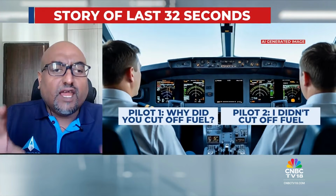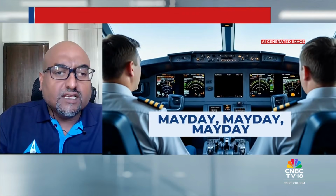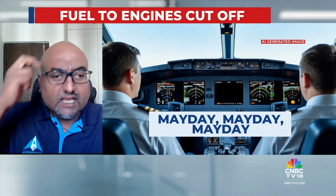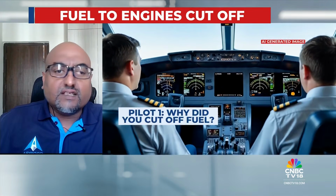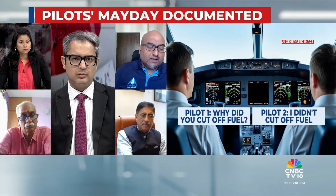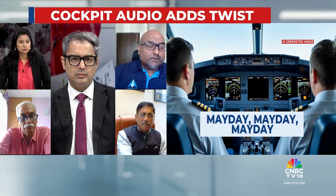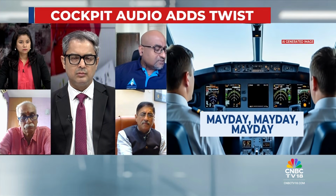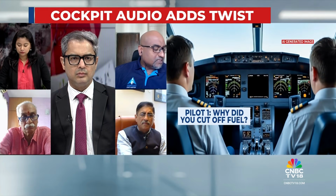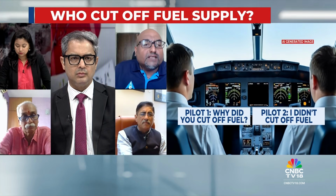Okay, first up, you're at 180 knots. You're at 800 feet, you had your takeoff thrust, you lost both engines. Now, when you lose both engines, that's far more significant than cutting off your fuel. Your fuel cutoff switch, you've got to pick it up, put it over the bridge, and then put it down. Now, there's no chance in hell that the fuel cutoff switch is going to automatically trigger unless there was severe vibration on the aircraft that triggered something to push it back.